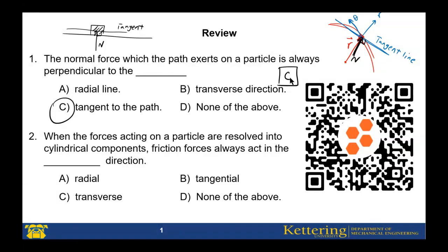For the second question, when the forces acting on a particle are resolved into cylindrical components, frictional forces always act in the... I explained also that if this particle is moving in this direction, the frictional force will be along the tangent line in the opposite direction of the motion.